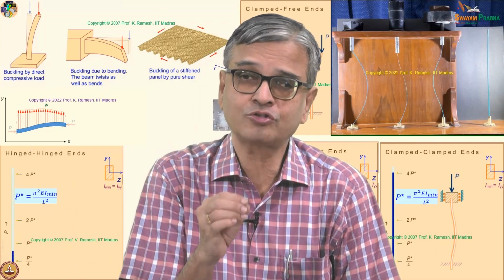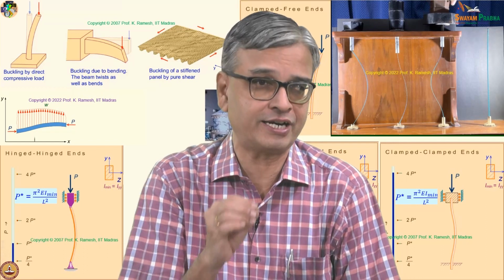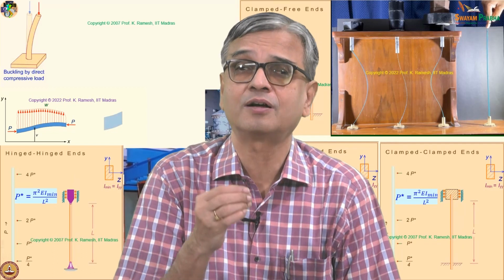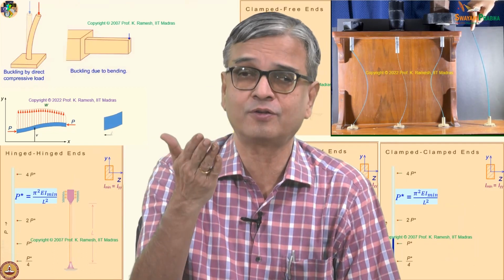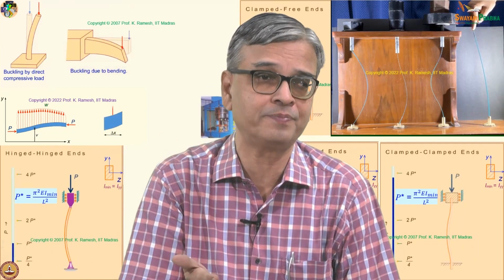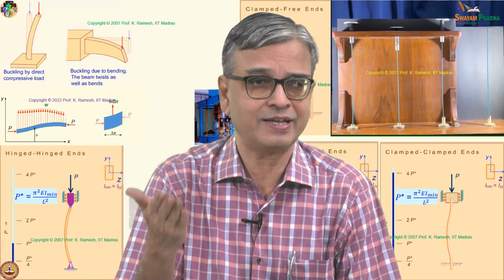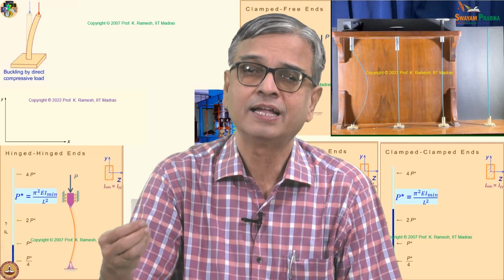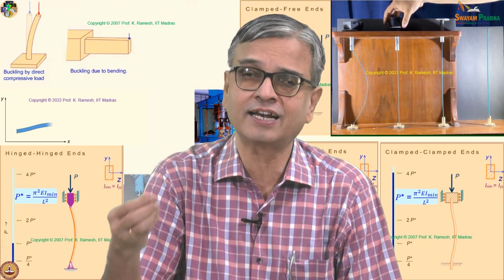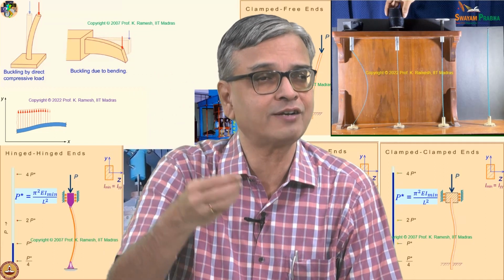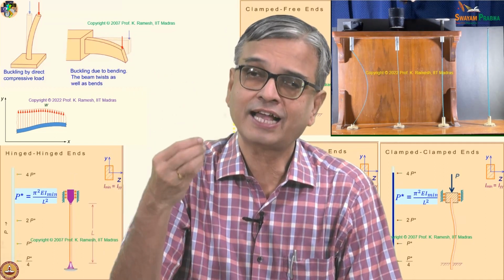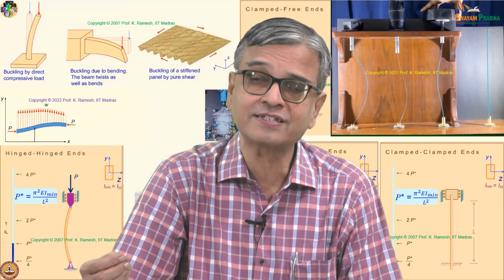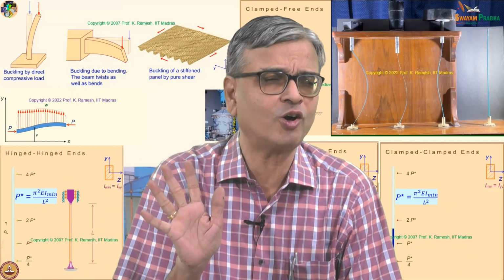Even though in this course we have seen support conditions, we have also looked at to what extent these supports modify your results. In fact, while we discussed the deflection problem, we had a truss. In fact, it was a frame. It was fixed at one end, the I-beam. We calculated considering that as a pin joint and then calculated the deflection. We calculated again the same problem with that as fixed. The difference was about 2.5 or 2.7%.